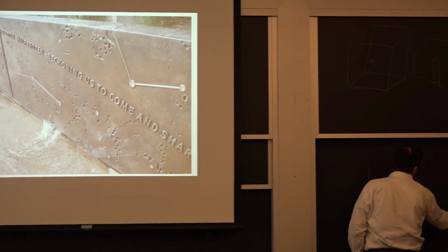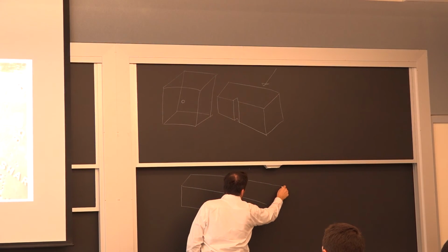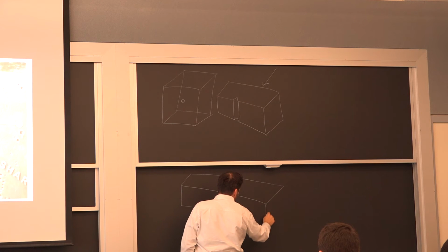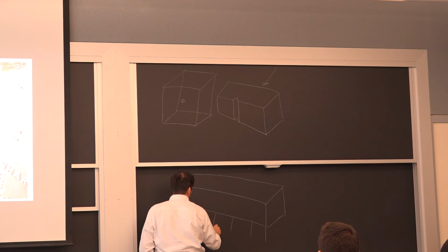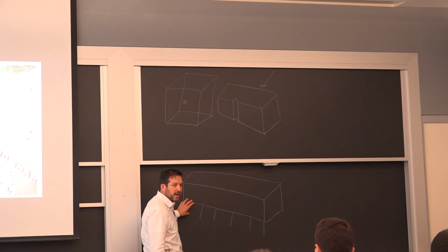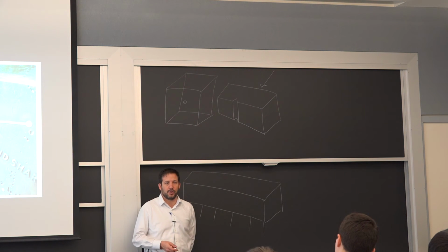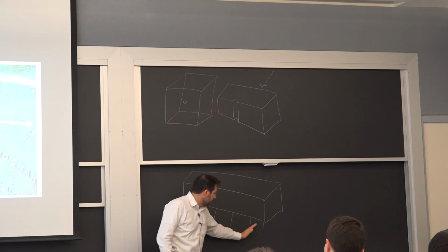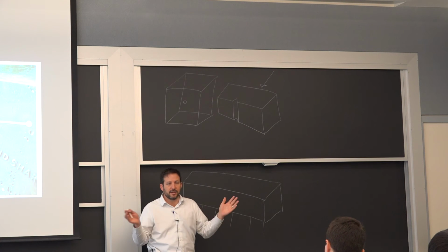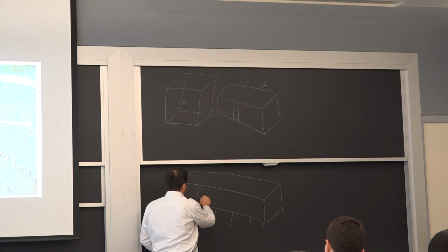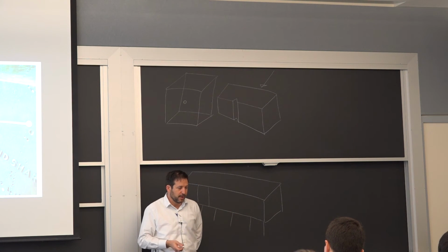So we put this here, and there's a lot of mechanical system inside that tunnel that we don't need to worry about here. But it is sitting on a foundation, so it's held by the ground at the bottom. It really had essentially a basement on the inside of it to host everything. So the bottom is restrained by the ground. The top really wants to expand and contract. Each panel, 8 feet long, is trying to go somewhere. And it's a big issue with buildings.